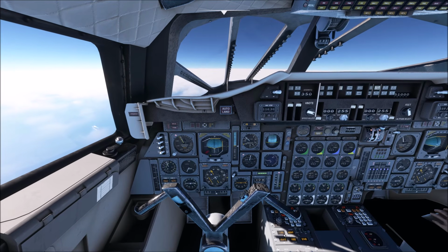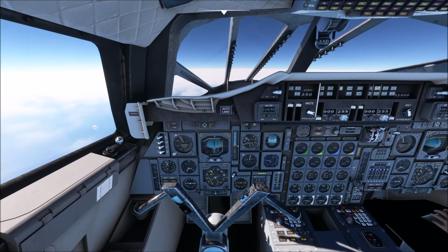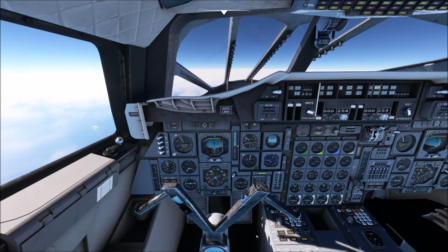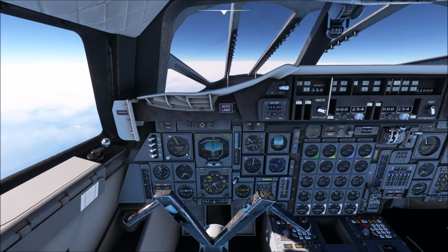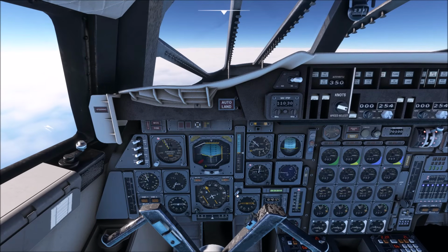Mach 1.93. As you can see, we're in super cruise, so it's now just a waiting game to gain the altitude, which as you gain altitude the Mach number will increase anyway because your ground speed will increase. Indicated airspeed 620, but our ground speed 1091 knots. So we've probably got 2,500 to go, so we're approximately 2.5 hours away from New York now. And again, as we go higher, that will increase, so our ETA will reduce.